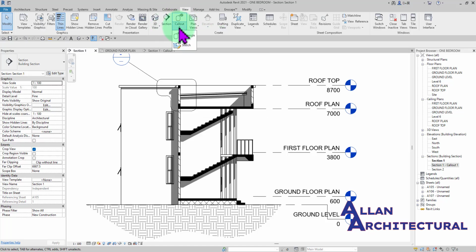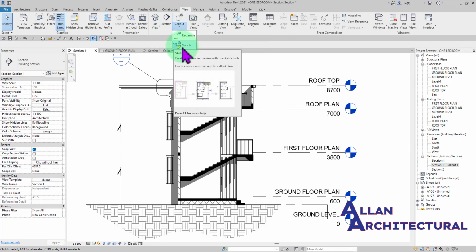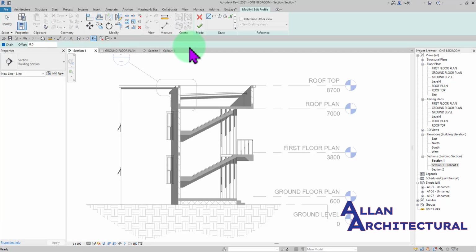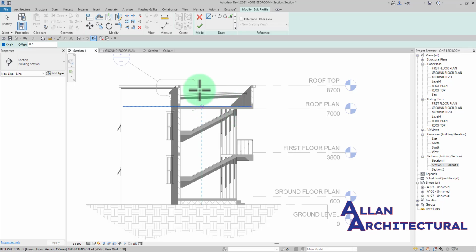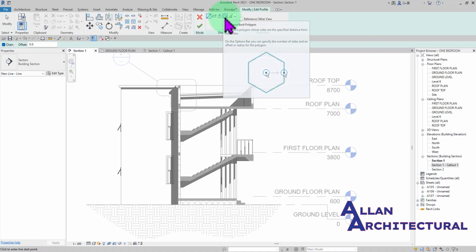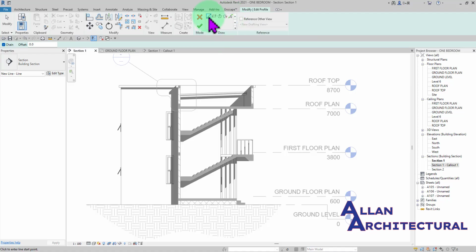So I'm going to click on that drop down menu, and then I'm going to select that sketch tool I have in here. All right, so this is perfect. So now Revit gives us this draw tool. Not all of our draw tools where we have the spline line and all of that stuff. It just gives us the line, the rectangle, the inscribed polygon, and the circumscribed polygon, and also pick line tools. All right, so I'm going to do the line, the basic straight line.